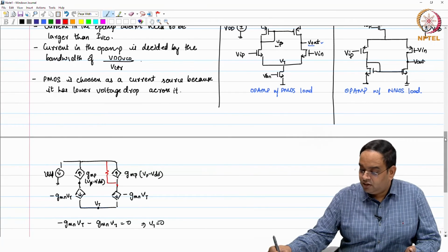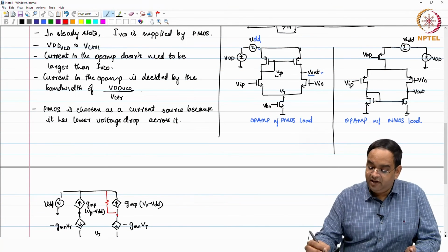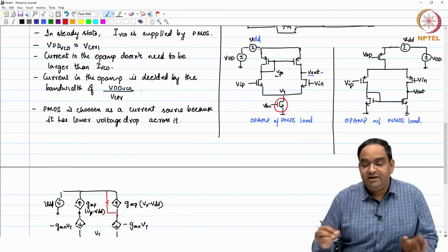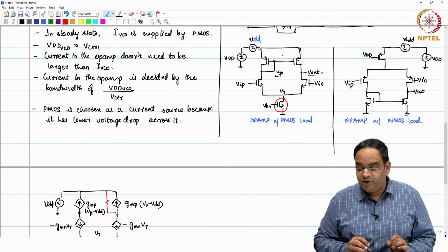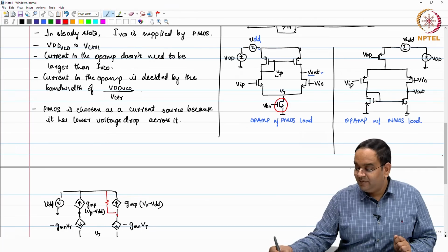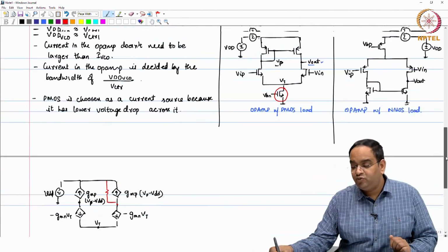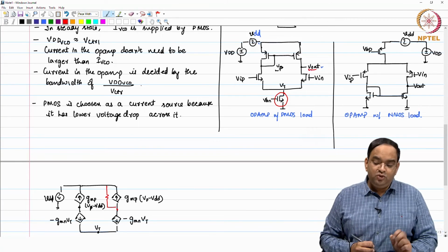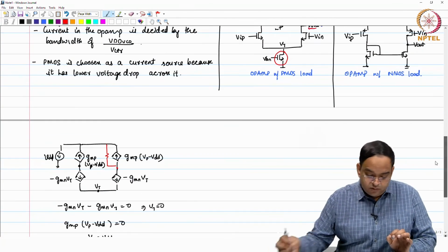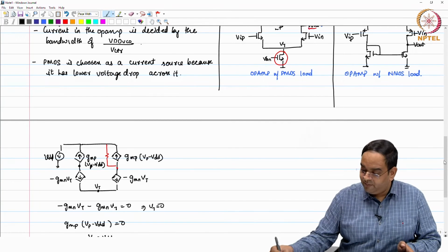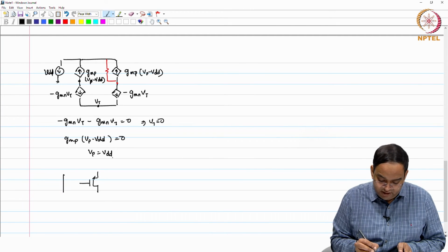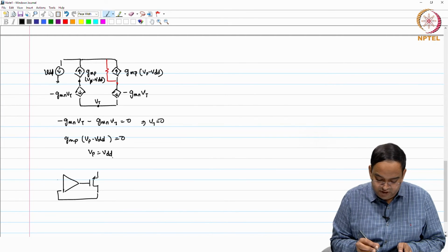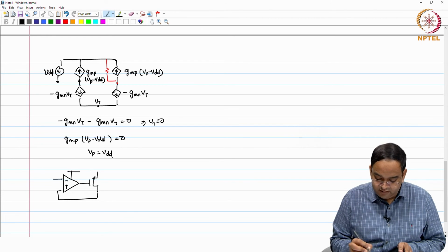So, overall, the assumption in this analysis we have made is that the NMOS offers an infinite resistance, first thing, because supply noise will act as a common mode noise here. And then, simplifying our analysis, you can do a detailed analysis, you will find that V out will be close to VDD. Now, when we club this particular amplifier with our PMOS, just think about it, that you are using this amplifier with PMOS like this, and you are having a supply noise in both the cases.